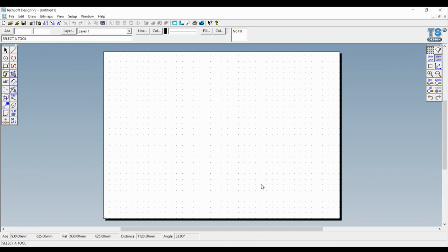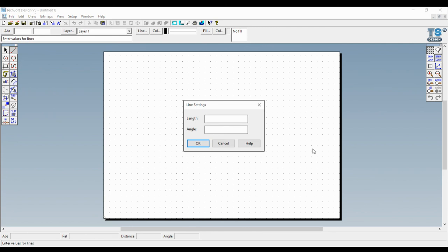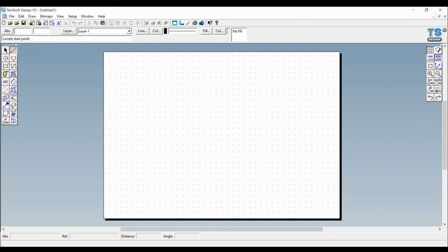As soon as you click OK, the A3 page on the screen will now be set to 1:5. So if I double click on the line tool, I can type in the length of line that I want. For example, if I want to draw a 200mm by 200mm box, that's the size it's going to be in real life. If I type in 200 by 200 and go to grid lock, which keeps it on the grid, you will see it gives me that line set at a fifth of the size, but using the real life measurements, that is 200mm. However, on screen, it's a 1:5 scale.